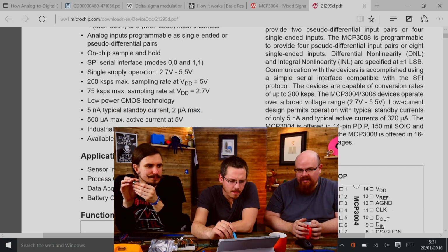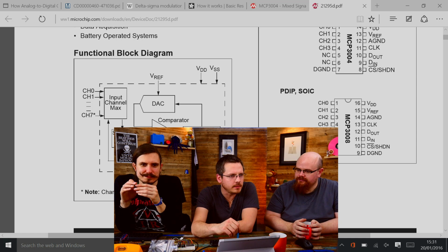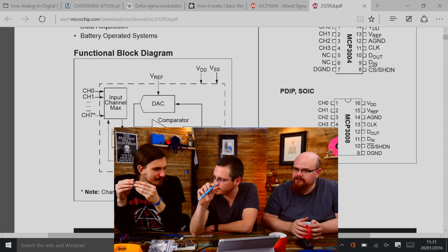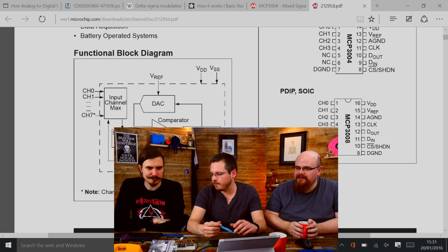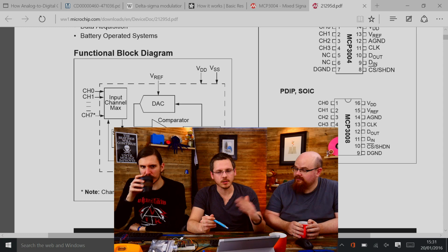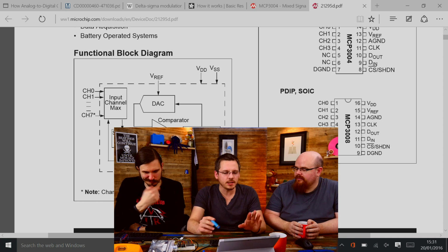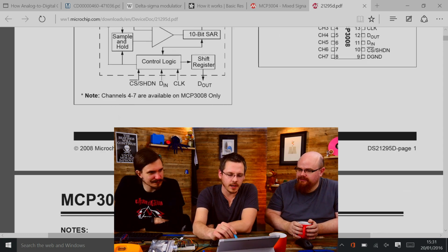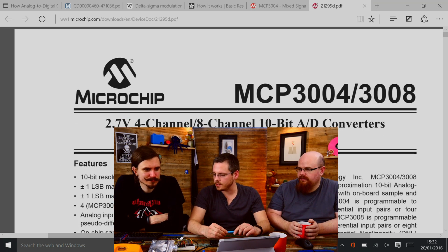So this is stuff where we really wish we were electronic engineers. Yeah, well, it's the kind of thing where if you need to know it, you can go and find this stuff out. But if it's not something you bump against, we tend to use ADCs for hobbyist stuff, so things like light sensors or this audio input. That's where they're primarily useful for us. Servos for getting the feedback as well, so that you can measure the position of a servo and stuff like that. So they're much easier to use than this datasheet suggests for most uses. It is basically just a way to sample some sort of analog value from the outside and turn it into something you can write code against.